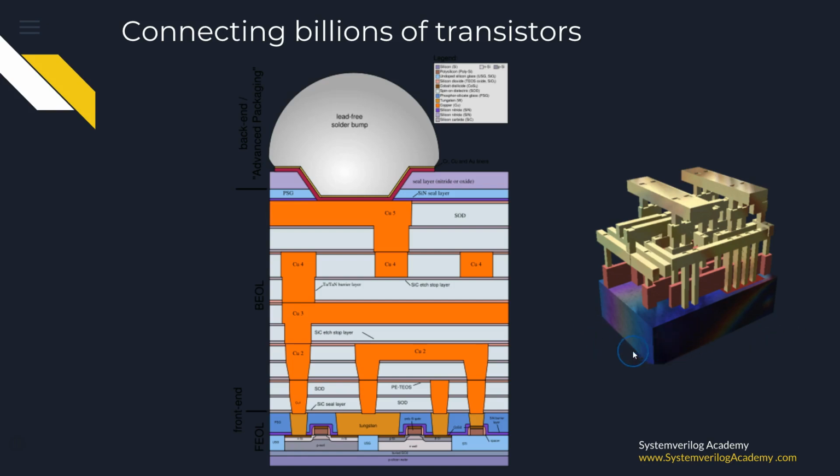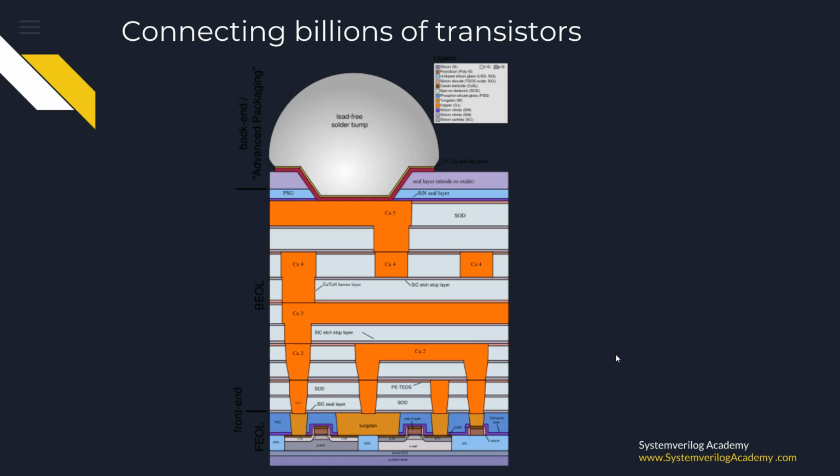From these descriptions, it is clear that you need 2 types of database to manufacture and connect transistors. First, the photomask to make billions of transistors in silicon, and second, the connection information between these transistors over multiple layers. These 2 complex requirements are solved in the physical design process and will be available in the GDS2 formatted database.